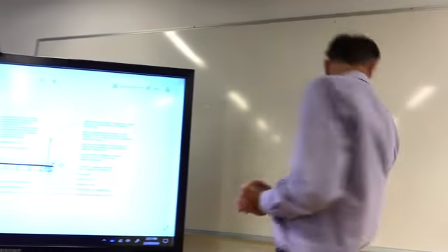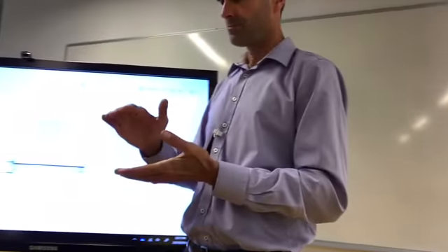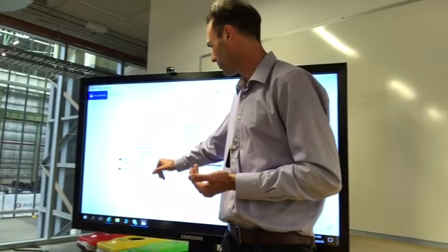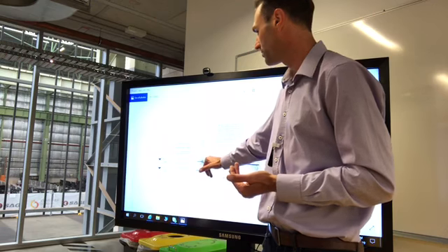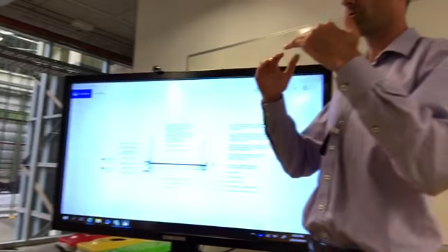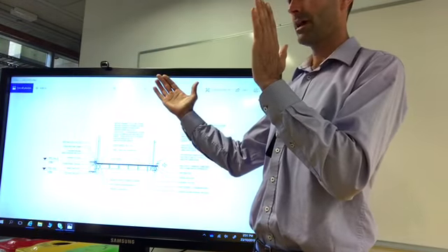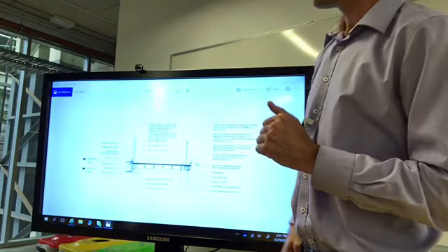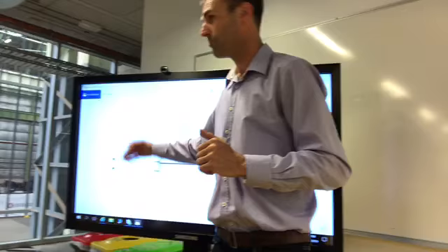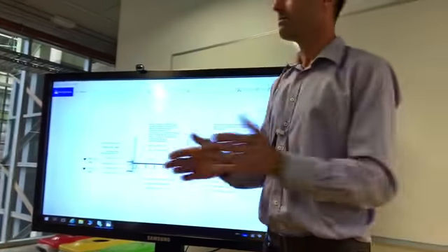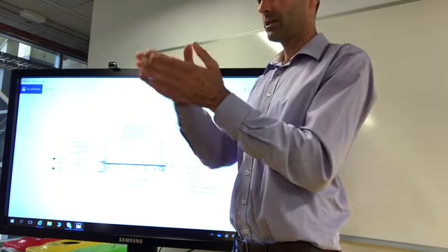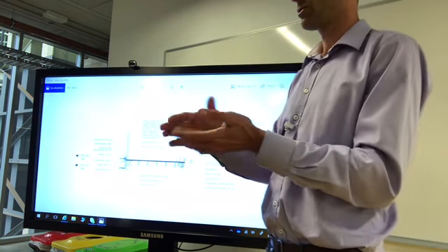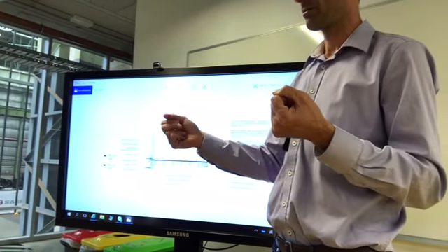So we're going to want to include our reinforcing at the top over this point at which our concrete exits our building. That's going to be the majority of that reinforcing. With a slab spanning from point of support to point of support, the majority of your reinforcing is at or toward the base of your slab, because that's where your concentration of tensile forces is greater.